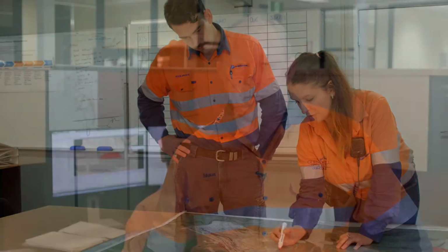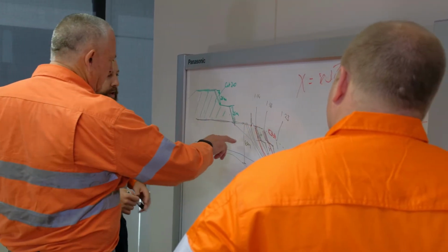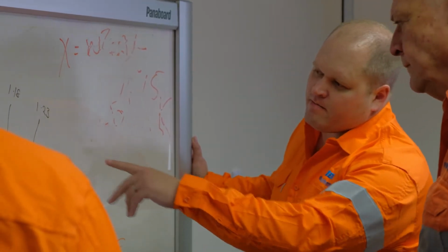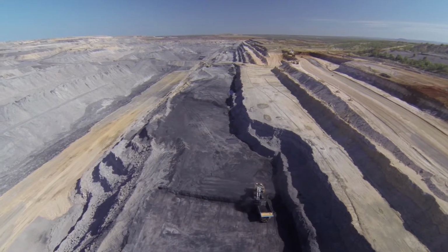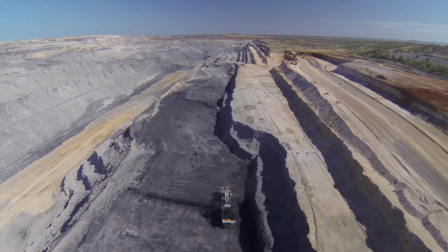Best practice is for geotechnical engineers to produce geotechnical design standards that mining engineers can reference to determine whether proposed slope designs meet predefined design acceptance criteria. Some sites include this information in their ground control management plan. Geotechnical design standards should include details of specific slope geometries like maximum batter angles, maximum bench heights and minimum bench widths for anticipated geotechnical conditions.